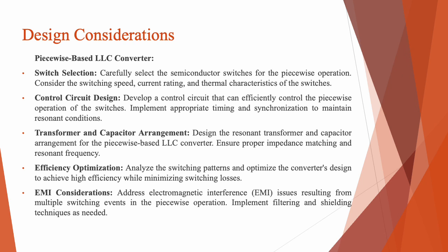The fourth one, the efficiency optimization. Analyze the switching pattern and optimize the converter design to achieve high frequency while minimizing switching losses. Fifth, EMI considerations. Address electromagnetic interference issues resulting from multiple switching events in the piecewise operation. Implement filtering and shielding techniques as needed.